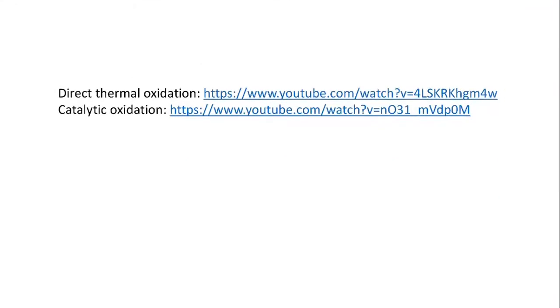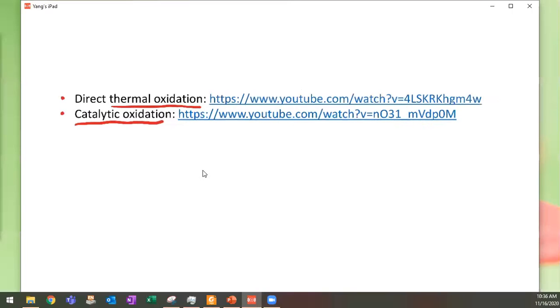So in terms of VOC control with this combustion or oxidation method, there are again two ways, right? We mentioned that there's direct combustion or incineration. This is called direct thermal oxidation. And we can also add a catalyst to this process, which generally allows us to operate the reaction at a lower temperature. Here I have two short videos showing how these two processes work. Then we can take a look here.